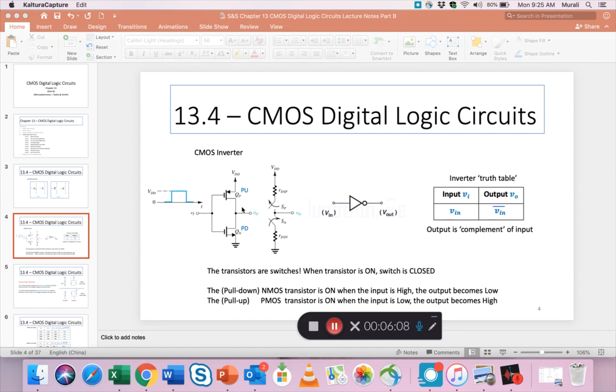And also I'm showing the fact that transistors can be thought of as switches, right? A switch with a small resistance, and a switch here with a small resistance. So particularly if you are interested in using the transistor purely as an on and off device, that means operation either in cut off, or triode, meaning fully on, and not in the saturation region in the middle, then the switch representation is important to have in mind.